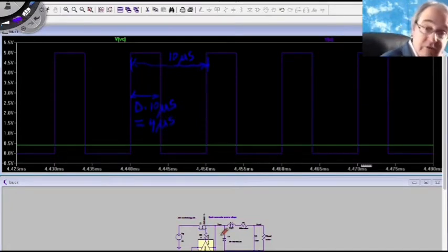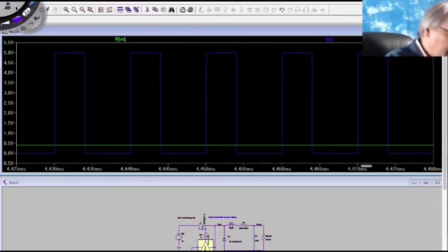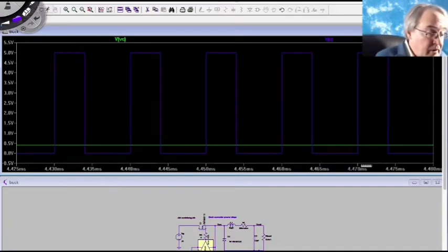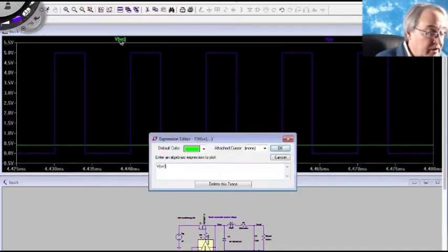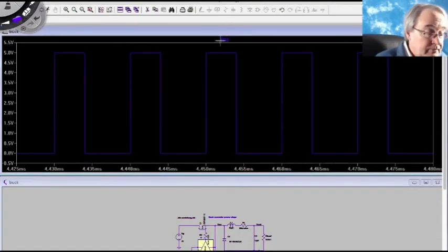Okay, I'm going to erase these waveforms, and now we'll look at some converter waveforms. To erase a waveform, right-click on the name of the waveform on the plot. So right-click on the PC, or tap the trackpad with 2 fingers on the Mac, and select delete this trace.